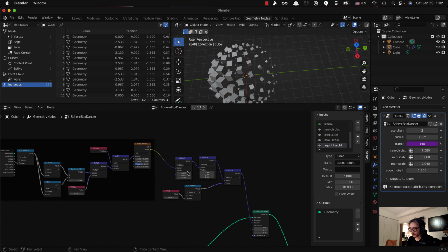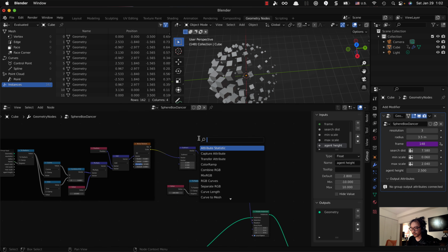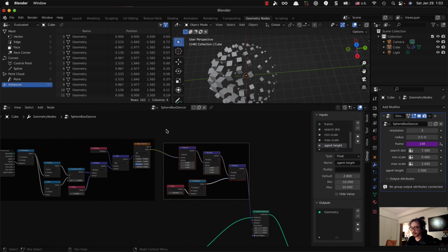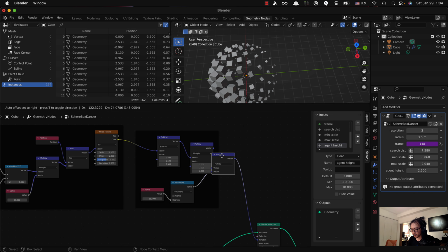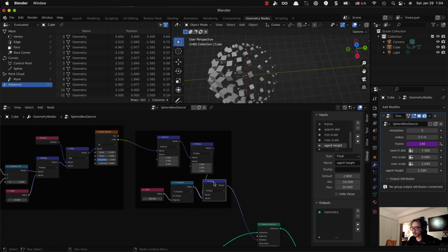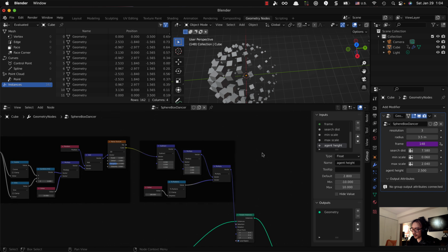Okay, now let's do the same for all this one. Create another frame, Control P. If you want to remove the node from the frame, you can click one of the nodes and type Alt P, or on Macintosh it's Option P. Okay. Or if you want to put this back into the frame, you can also drag this inside the frame and then it will automatically attach to the frame.